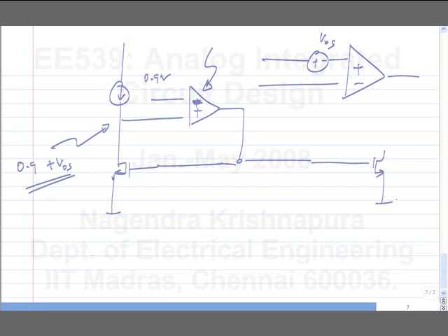But that can be an issue also sometimes. So the bottom line is you design your circuits to minimize systematic offsets, but random offsets is something you can't help. That is, at least you certainly don't know the exact value of random offset. The only thing you can do is reduce the sigma of the random offset if that is bothering you.